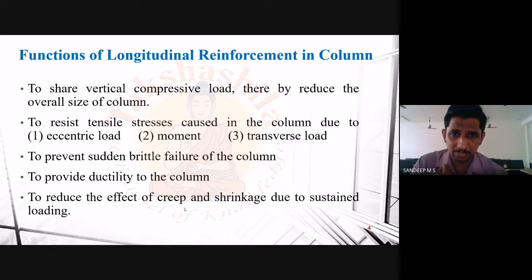Then, to reduce the effect of creep and shrinkage due to sustained loading. Normally, if we are not providing the longitudinal reinforcement, the effect of creep as well as shrinkage will be very high. And we already know what creep and shrinkage are. So when we provide the reinforcement, the effect of these two quantities will be reduced. That is another function of providing longitudinal reinforcement in a column. Any doubts in this?